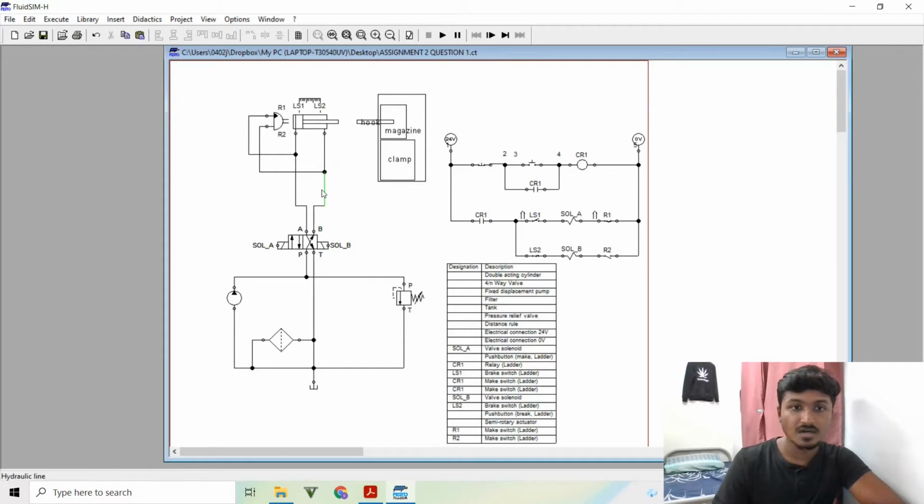After we activate the 4/2 double solenoid valve, the cylinder will advance and grab the end of the hook, and with the help of the rotary actuator it will twist it 90 degrees. Then, still holding it, it retracts and drops it. Then the cycle follows, and the hook is manually input into the magazine.